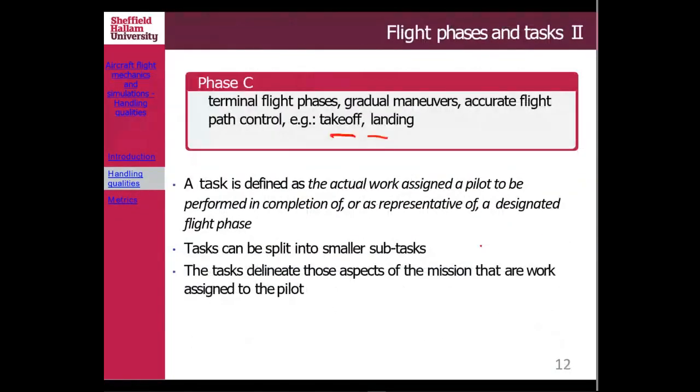If I could just conclude this, when you define the task, you need to make sure that the task could be performed by any pilot involved in this flight test. If you try to assess handling qualities and you define a task that only a certain test pilot could do, then the assessment will not be objective, right?